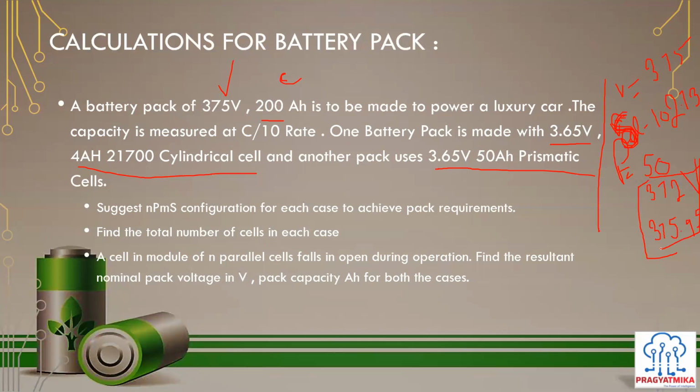Exactly. So in case of larger battery packs, this is a business thing. It is not a technical thing that I'm talking about. Practically, in the case of larger battery packs, this is for a car. That's what we are making, right? And for cars, the powertrain voltage starts from 350 volt and goes up to a 400 volt limit. So even if we take 102 cells in series, there is no impact on the powertrain or the capacity, because relative to the total voltage range, a difference of 3 volt in the nominal voltage will have a very small impact, right?